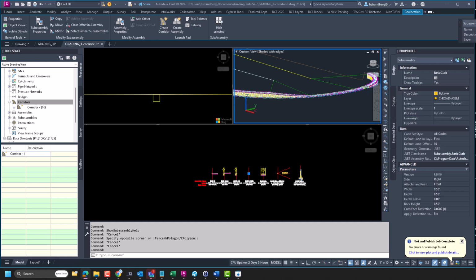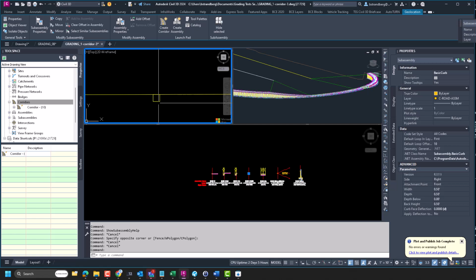Now let's talk about feature lines. Because we need to be able to tell left from right at a glance, I created my feature line styles to use this guardrail line type. Right is the side with the boxes. So that makes it really easy for me to tell what I'm looking at a glance.